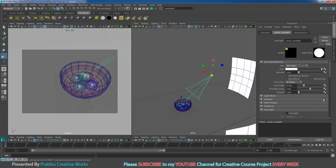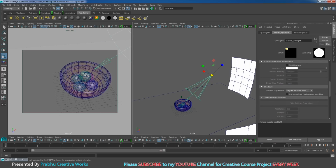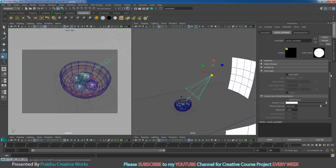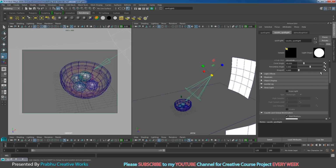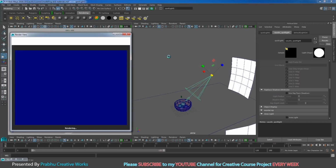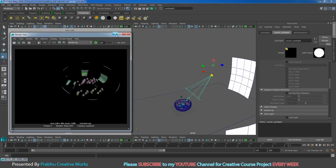So go to mental ray. On the bottom side you will have the option emit photons. It will emit photons for our caustic light. Then go to the shadow option and turn off use ray trace shadows. Now click on this viewport and click render. You don't see any changes in our scene, so I will keep this image for comparison.